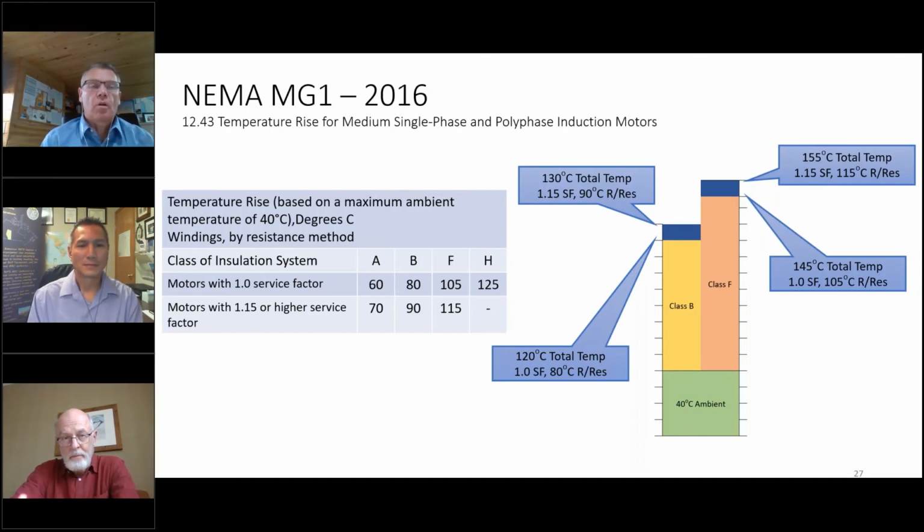You might want to see what current's being pulled without the load. So, typically you probably would see no more than 2 or 3 amps uncoupled. If you're seeing something else, is that a misalignment? Is there something else? Is something pinched? Is something rubbing? Those are things you can look at. So looking at coupled current draw and uncoupled current draw will indicate some of the torque requirements.